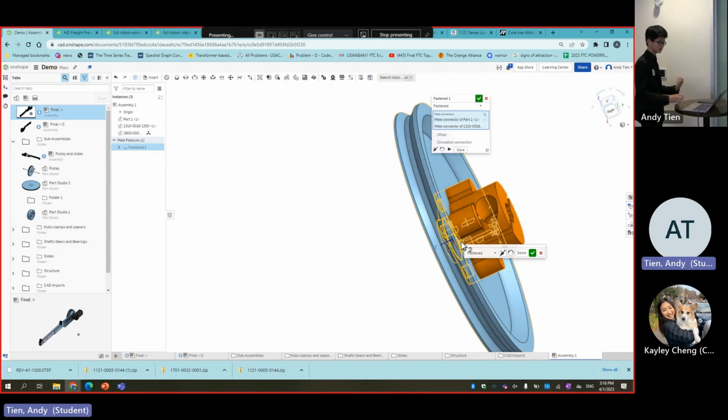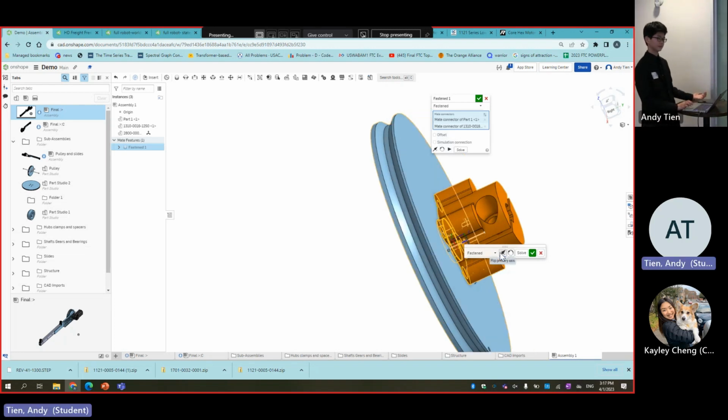How we fix this is with the quick adjustment functions that Onshape provides. Namely, you can flip the part and you can rotate the part. If I click flip, you can see it now flips into place. But say this was a more complicated part, I could also rotate the axes by 90 degrees until it fits. You can see the little hole that I've created shifting as I click this by 90-degree intervals. For finer adjustments, you can also click offset.